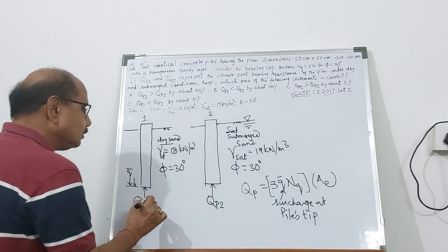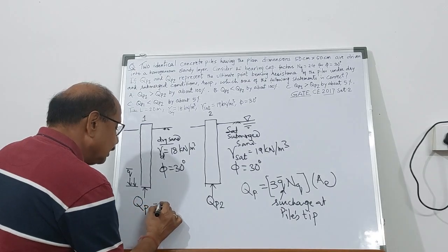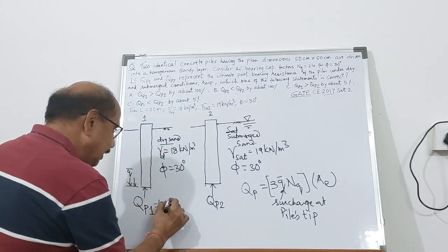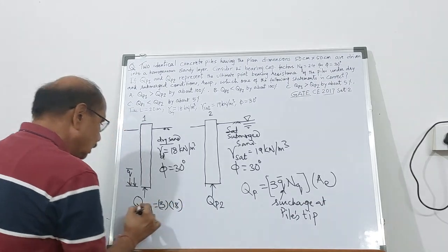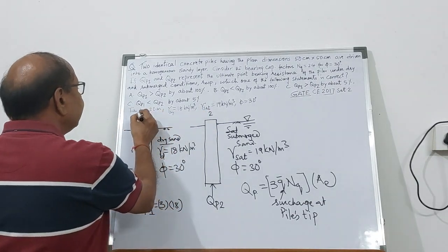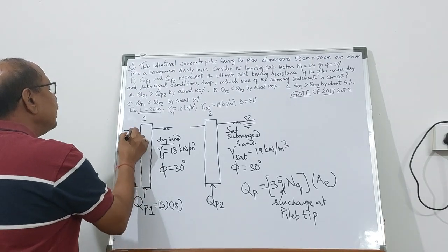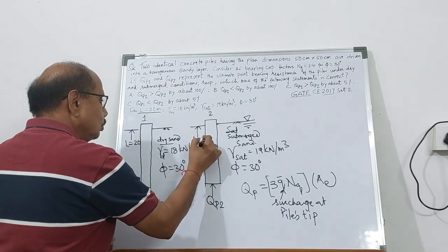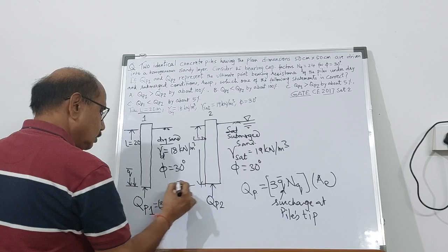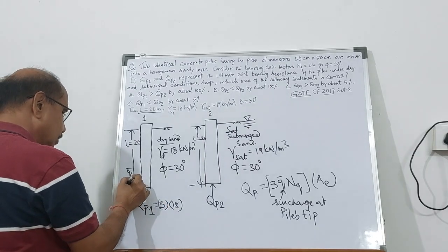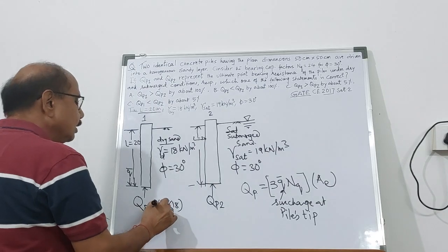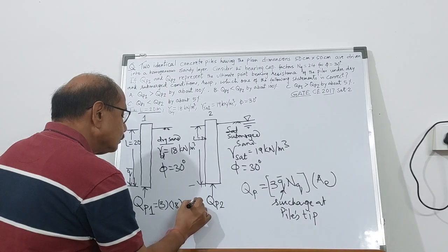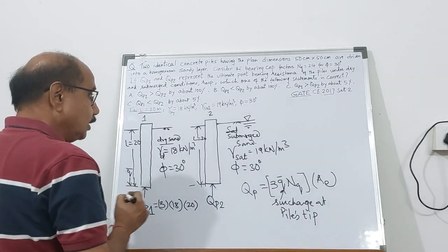So calculate this one. So Q bar will be gamma D, that is 18, multiplied by the length of the pile, given here as 20 meter. So this is L equal to 20 meter. Here also L equal to 20 meter. So length of the pile is known to us. Therefore, the surcharge here is going to be 18 into 20, right, into NQ.